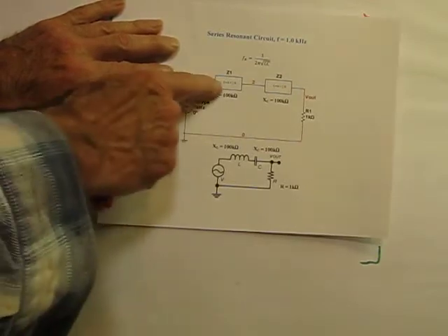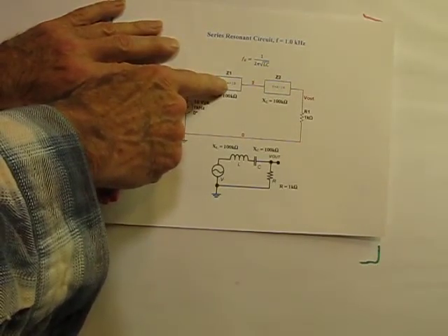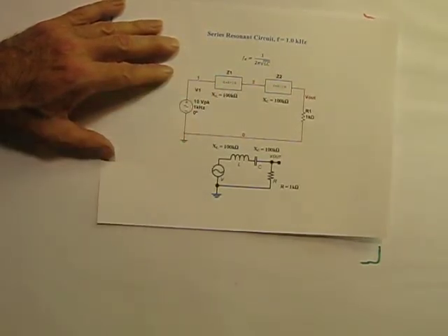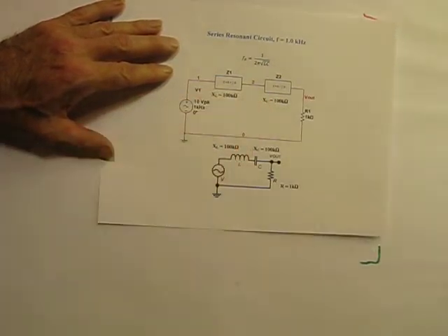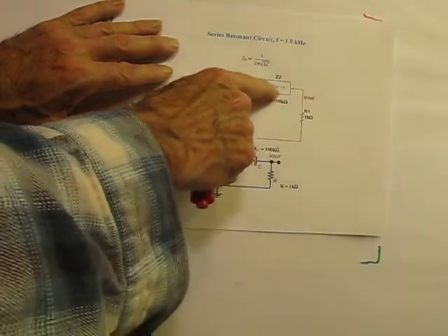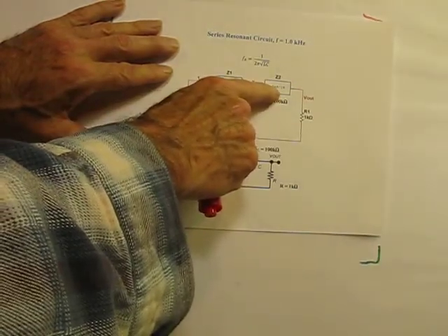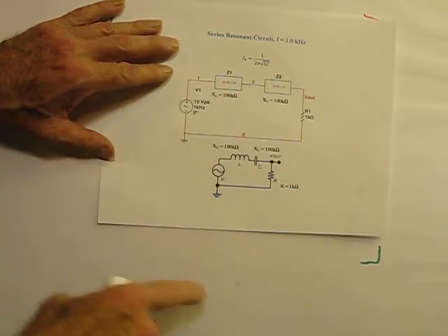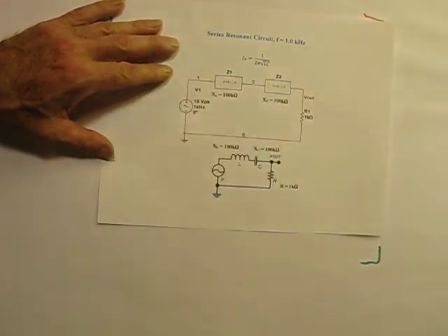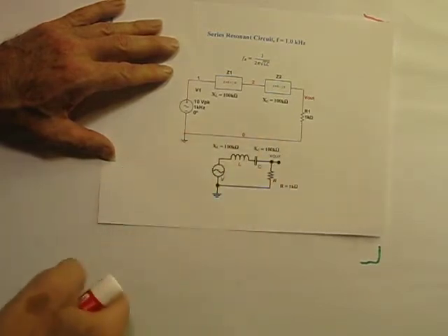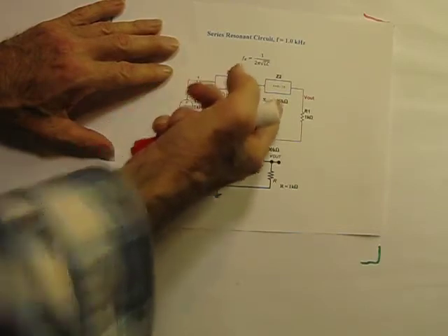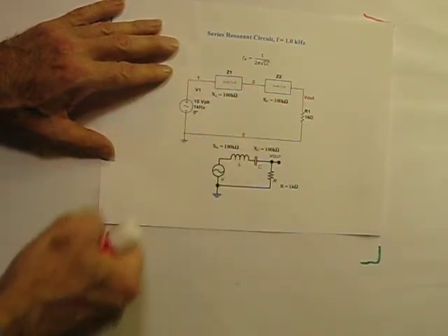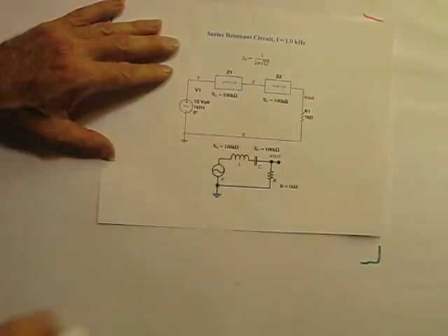So in the block here, the A would be equal to R, and I made that like 0.01 ohms, and then set the inductive reactance for 100K, and likewise for the capacitor impedance block. And notice this is A minus JB and A plus JB, and here's a V out across resistor 1. So the equivalent circuit of this I drew below because these blocks are a little bit confusing. It's nice that you can enter the reactance directly without having to figure out the C values like I would do for the circuit down below.